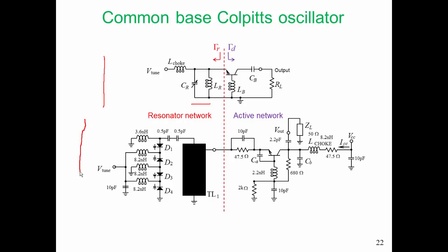The particular form of the oscillator that we're going to design in this case study is as shown on the bottom here. We've arrived at this transmission line resonator here to replace the inductor in the simplified topology. That transmission line has lower loss. You may also notice that this transmission line is tapped.